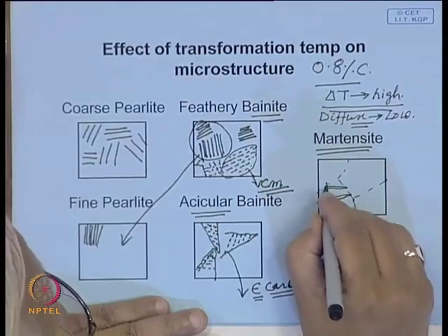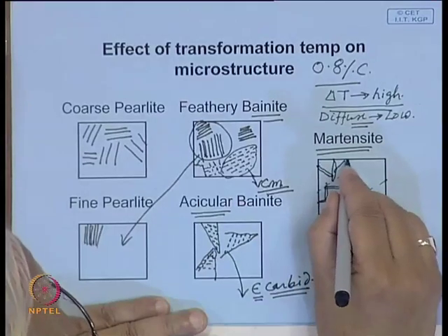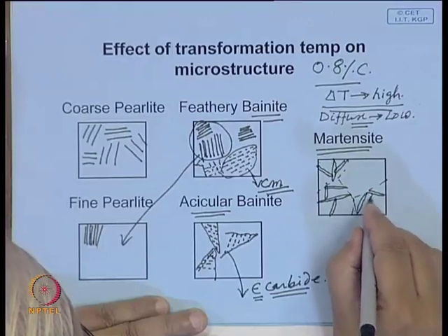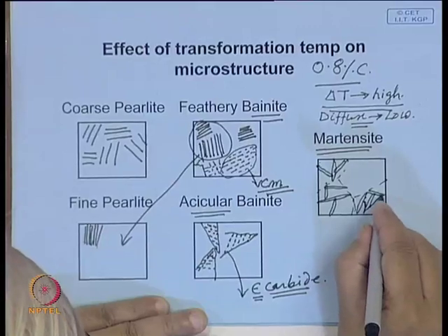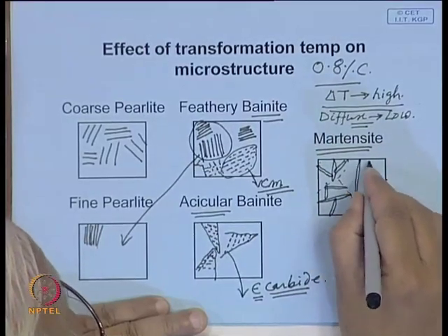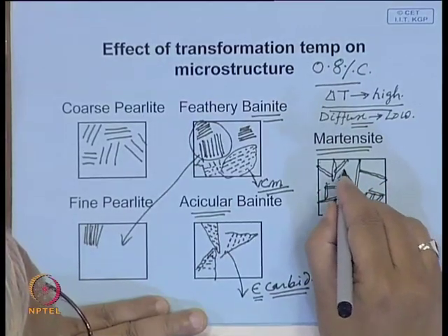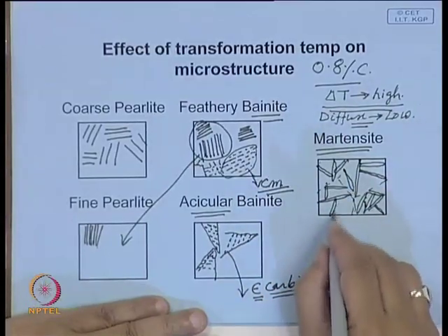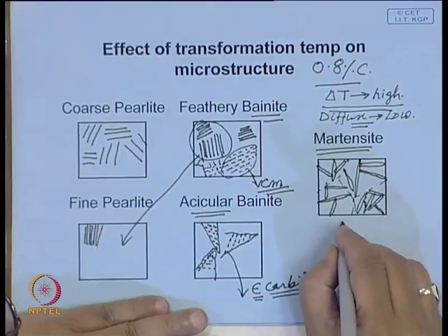They cannot cross the grain boundary, and these are single phase structures. Their fineness will depend on how large the austenite grain is. If grains are coarser, you can even see these needle like structures in an optical microscope, and this type of structure is called Martensite.